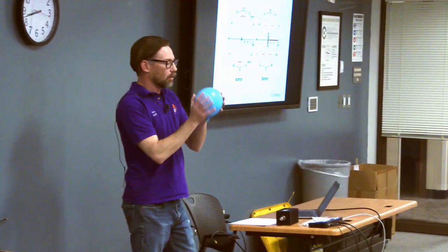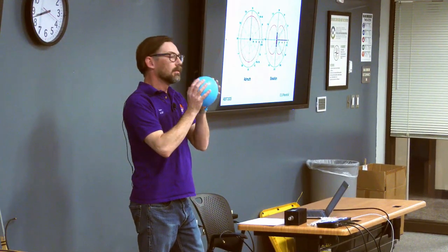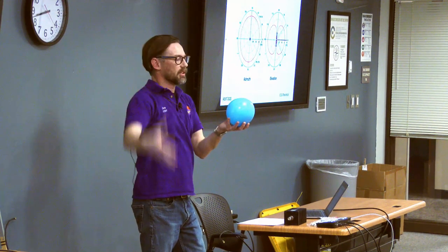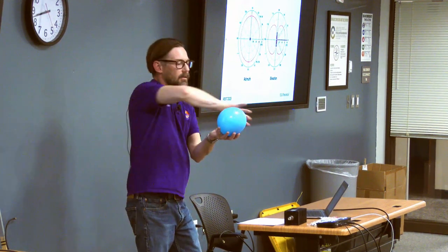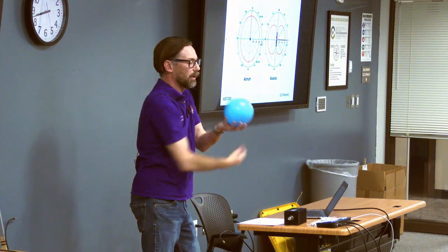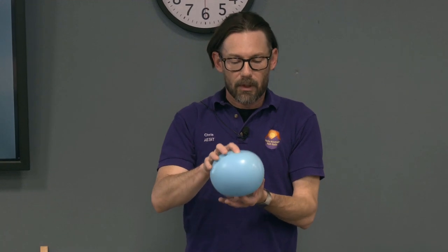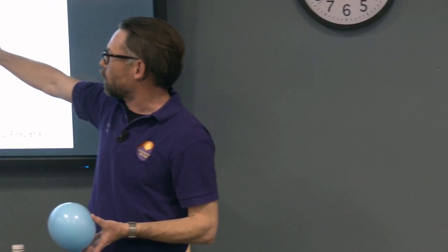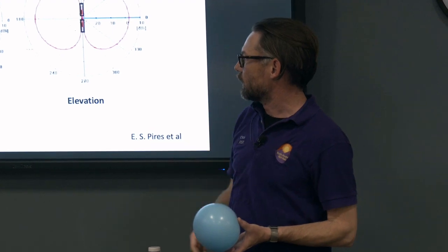Okay, so we have a real-world dipole antenna. It's not sending radiation out in all directions in a sphere. It's only sending it out to the sides, but all the way around. So let's talk about pattern. Because we have nothing going up, we can represent that here. In our elevation, this diagram is how we represent where the energy is going from a given antenna.